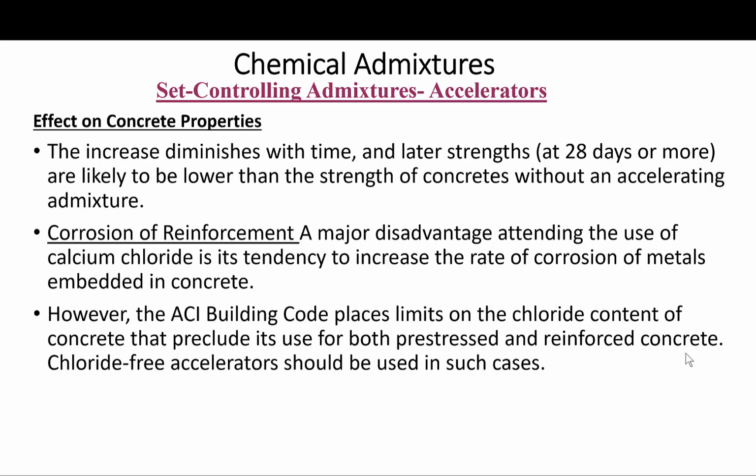Okay, with regard to the corrosion of reinforcement, as I mentioned, a major disadvantage of the use of calcium chloride is its tendency basically to increase the rate of corrosion of metals embedded in the concrete. And as I said, in the distant past, addition of calcium chloride up to 2% by weight of cement was considered safe to use in ordinary reinforced concrete, provided that an adequate cover of dense concrete was provided.